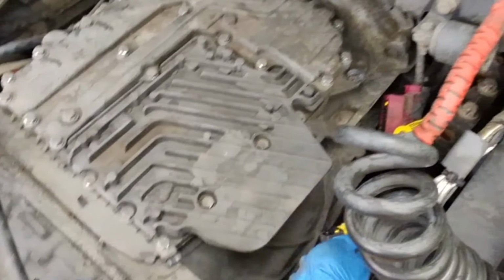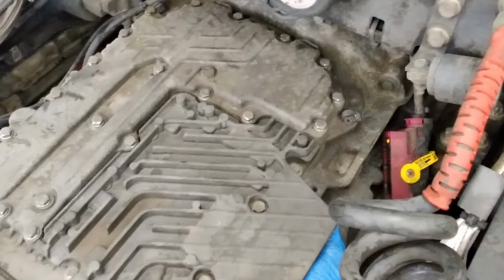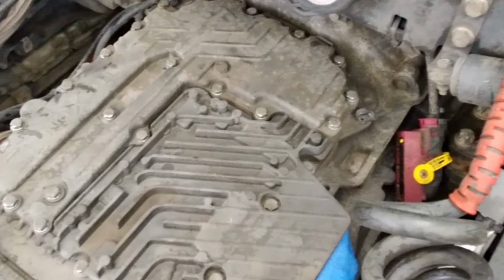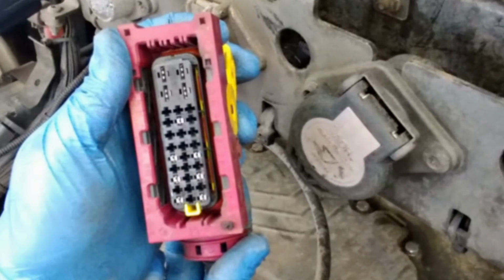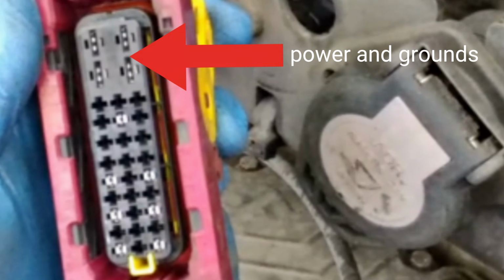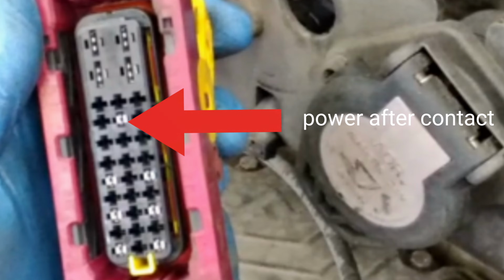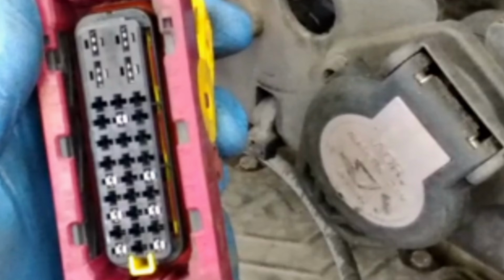This lead here is the output shaft speed sensor. It is a dedicated signal for Traxon and is connected to the Traxon ECU via an external loom. Lastly, as promised, we have the main gearbox loom and plug. The large connections, as you can imagine, are for the main power and grounds for the gearbox, whereas the other connections are for CAN communication.